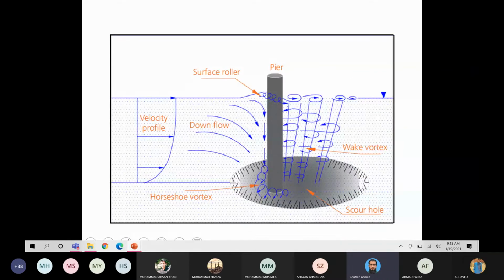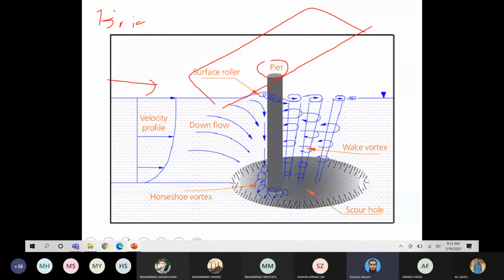So in terms of hydraulics, what are the drawbacks of these vortex flows in, say, a river? One example is bridge pier scouring. Okay, this is the pier of a bridge. Say you have some bridge on it, and the water is flowing in this state. This is the river bed. River bed means there would be a mixture of sand, clay, gravels, boulders, etc.